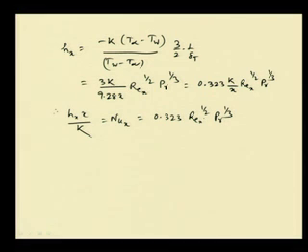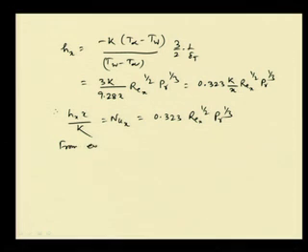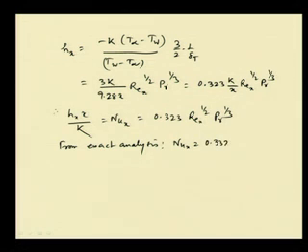This is the expression for the local Nusselt number, but from the exact analysis what we found is that Nu x equals 0.332, in place of 0.323, into Re x to the power half and Prandtl to the power 1/3. Already we have discussed this. Therefore, we can see that the expressions for the Nusselt number are very close to each other, whether we go by exact analysis or by the approximate method of analysis, assuming some velocity and temperature profiles.